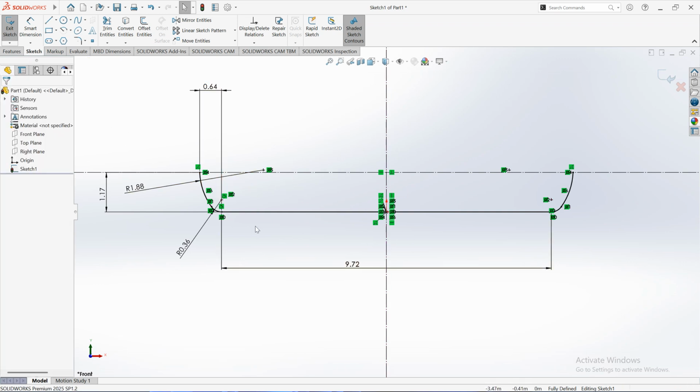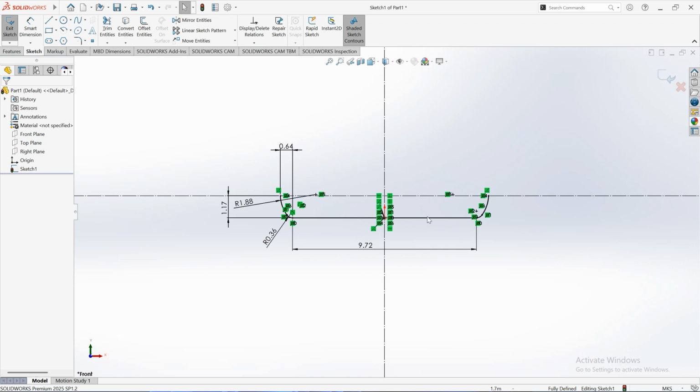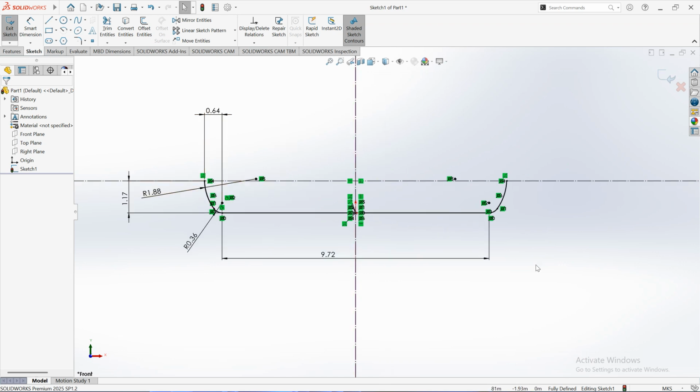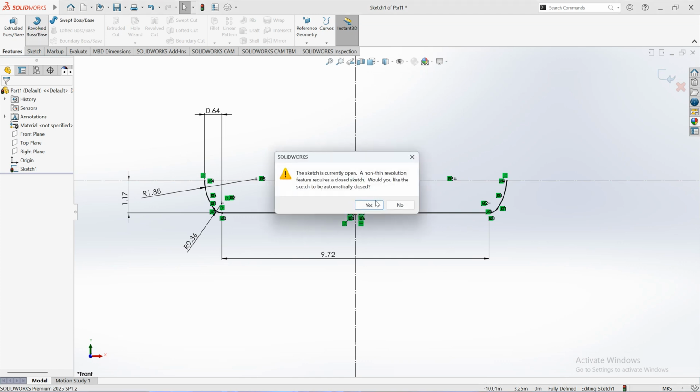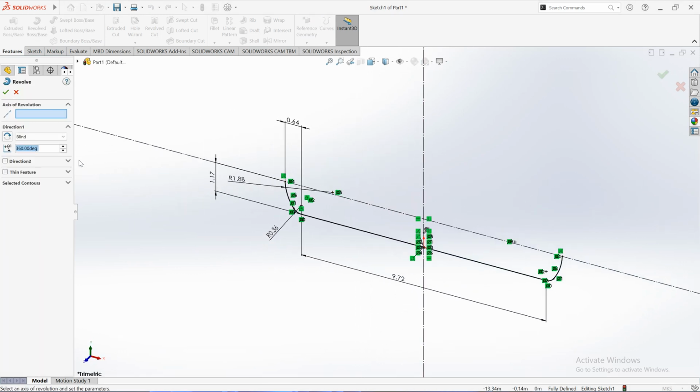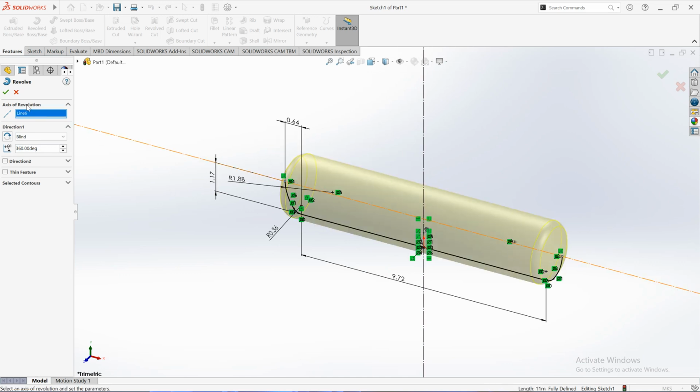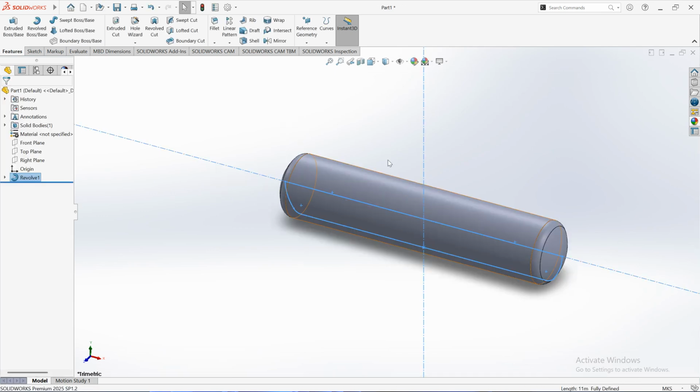I need to complete the tank drawing. Now remember, these dimensions are taken from inside the tank. So if I can find the volume of these dimensions, it means I have the volume of the full tank, okay. Now to complete this thing, I first need to turn this into a 3D model, okay. It's quite easy because I did the drawing this way because I want to use the revolve feature, okay. If I click on revolve, and if I give it the axis of rotation as this one, it automatically turns this into a 3D model for me.